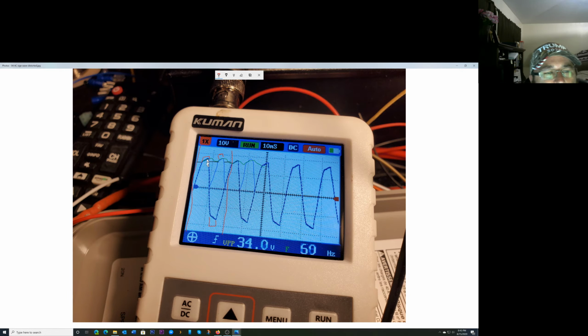When it does pull current, it's pulling its peak current to keep that DC bus charged up to 315 volts or 330 or whatever it is. It sags down a little bit when you put the load on there. So anyway, too bad some of those guys weren't on right now. We were all talking about this stuff, but this is in reference to those VFD drive videos I was making and what's going on and why putting on an amp clamp meter just doesn't do the job.